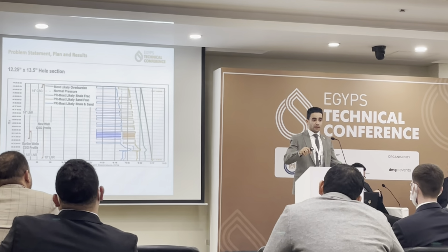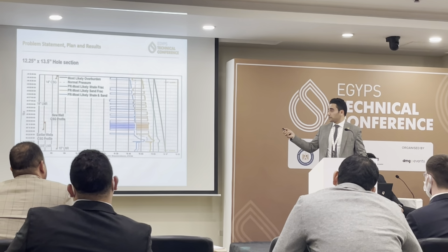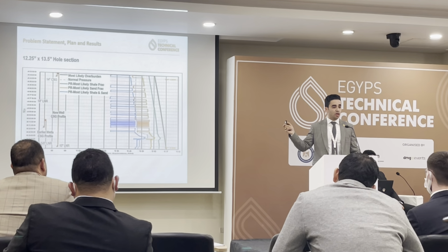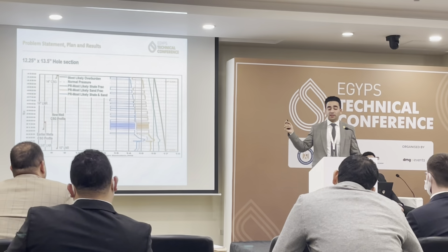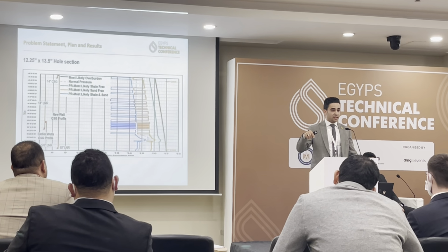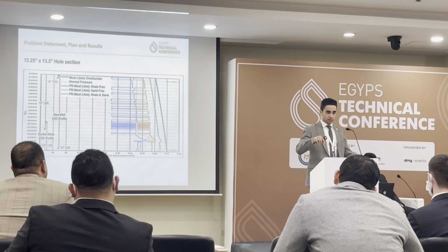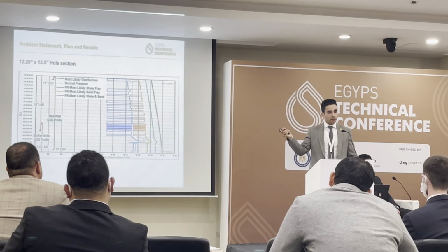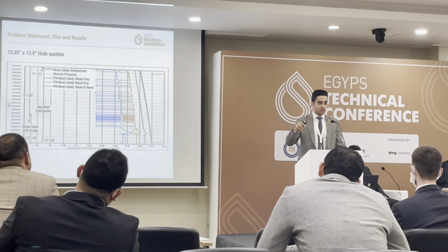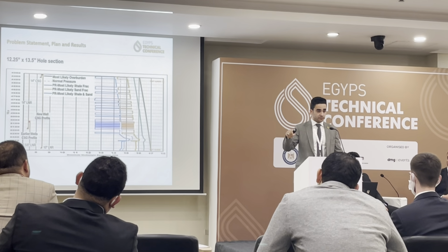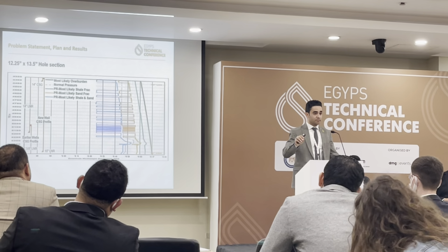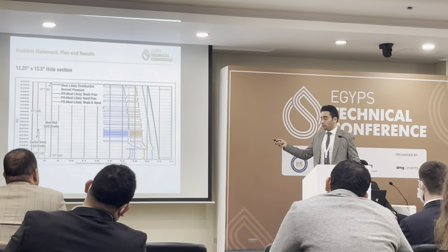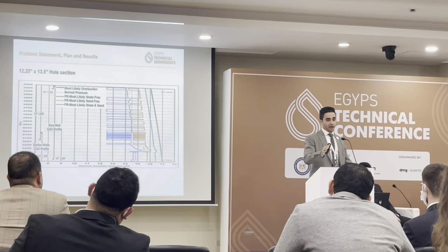We continued drilling till at the depth of 5,755, we decided to reduce the ECD even lower to stop the losses. We were drilling with losses. We decreased the ECD to 14.767. The losses stopped, but we got gas up to 30%. So at this moment, we had no margin between the pore and frac.